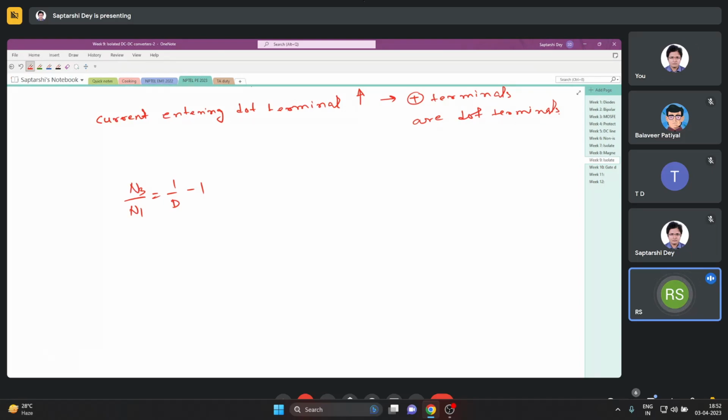Sir, my question is, we say the core in the flyback converter stores energy, and in the forward converter it won't store energy. Ideally, it doesn't, because Lm is infinite. When we say the flyback converter stores energy, are we referring to that minimum flux that the core attains every switching cycle? Based on that, are we saying half Lm Im square? I can understand your question. What is the question exactly?